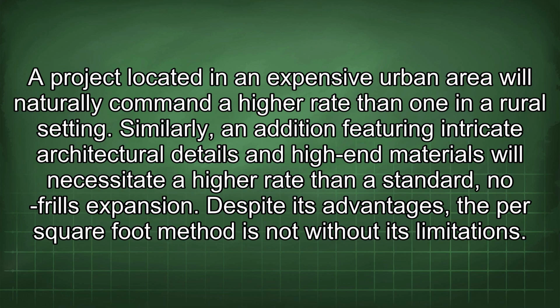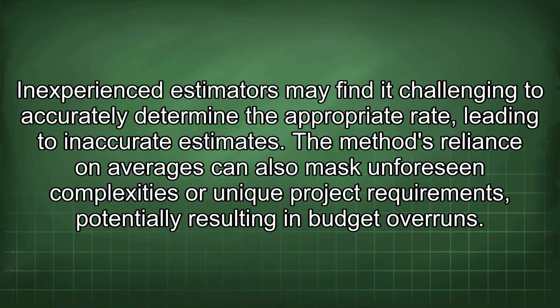Despite its advantages, the per square foot method is not without its limitations. Inexperienced estimators may find it challenging to accurately determine the appropriate rate, leading to inaccurate estimates. The method's reliance on averages can also mask unforeseen complexities or unique project requirements, potentially resulting in budget overruns.